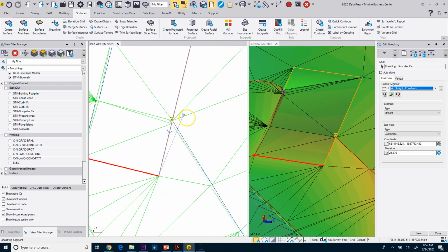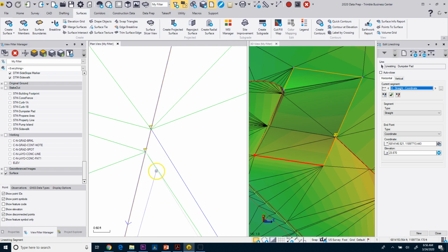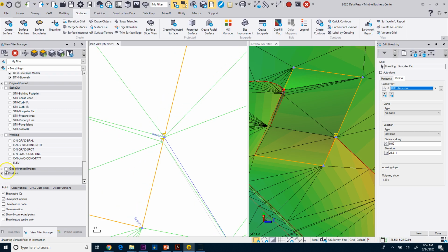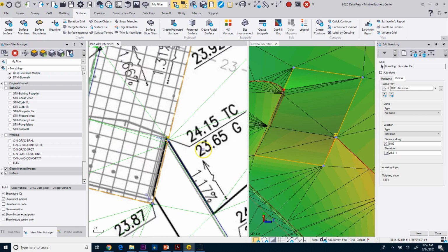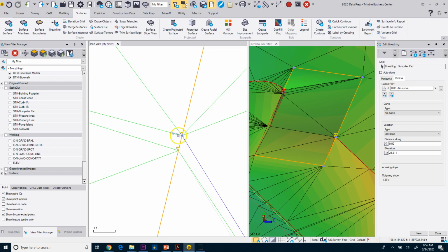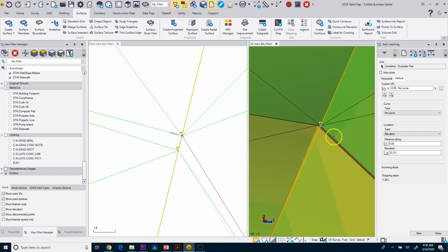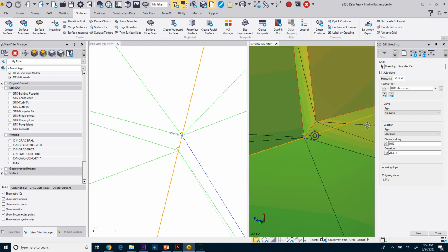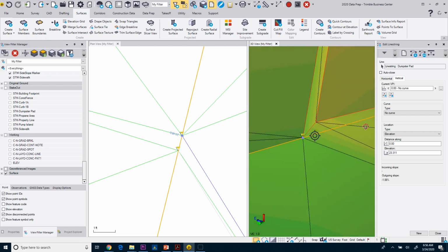Now these guys over here, right, what we can do, let's go to vertical. And we do have that point there. Again, if we turn on the reference, that point at the bottom should be 2365. That's the elevation that we want, 2365. So if we zoom in on this, like I had mentioned earlier, that top back may need to be kind of slid back a little bit.